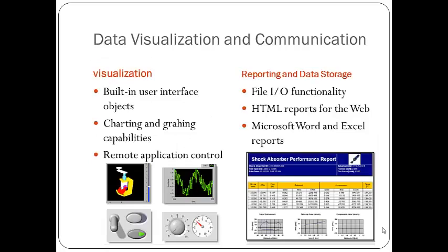Effective visualization and presentation of results is essential for making decisions, monitoring processes, and sharing information. LabVIEW provides many objects such as charts, 3D graphs, tables, and indicators, which you can drag and drop onto a front panel to display data and results.